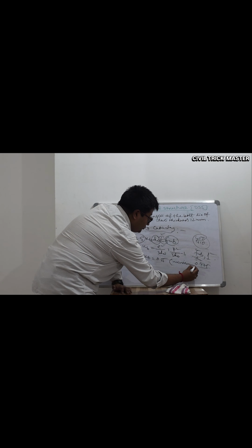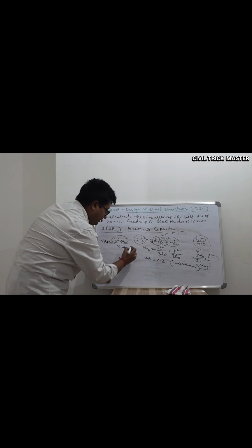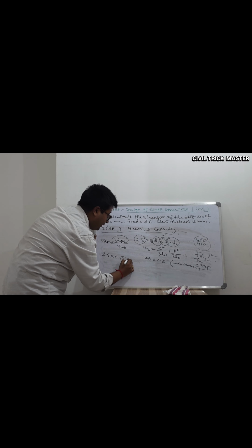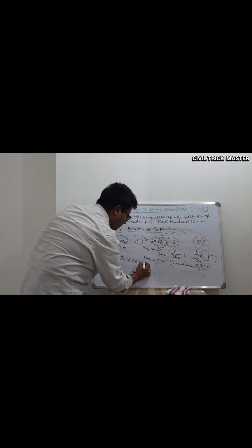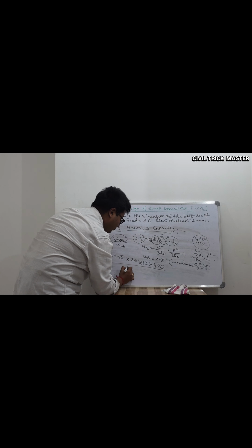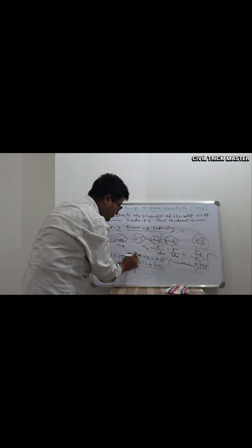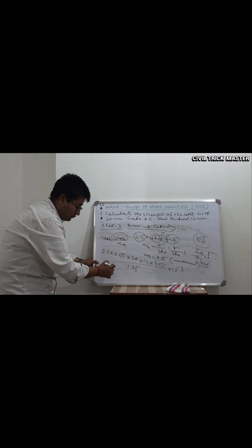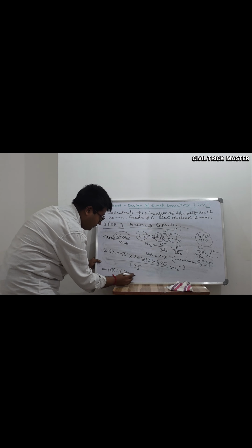After putting all these values, you calculate 2.5 into kb 0.55 into d0 that is 20, t our thickness is 12, fub that is 400, divided by 1.25, the gamma mb partial safety factor, into 10 to the power minus 3. After evaluating, you will get 105.6 kilonewton.